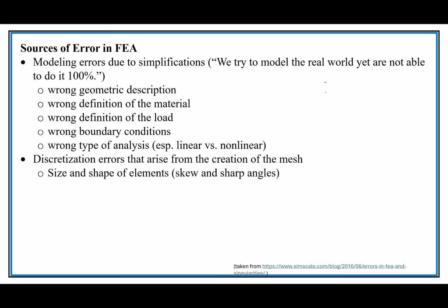see what happens when you make the mesh smaller and smaller. If it starts to converge, you can see that, up to a point where, okay, I get a better idea, I get a better feel, that's probably what the answer is for the localized stresses. But it could diverge as well, as we will describe in another class.